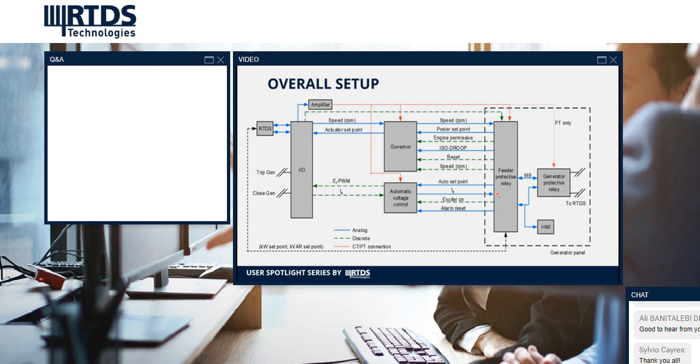Using the 751, any operator, although you can do this remotely from a central SCADA HMI, could go in front of the generator panel 751 and load and unload the machine. When you load a machine or turn it on for the first time, it would synchronize the machine and, in steps, slowly load the machine starting from 0 megawatts to 1 per unit, or wherever they want to go.